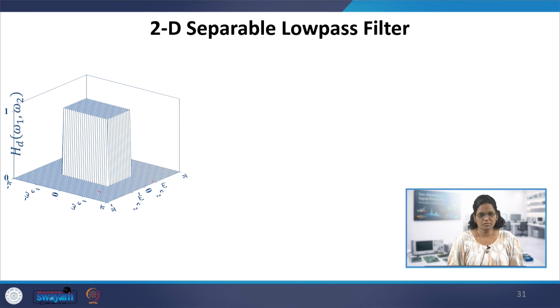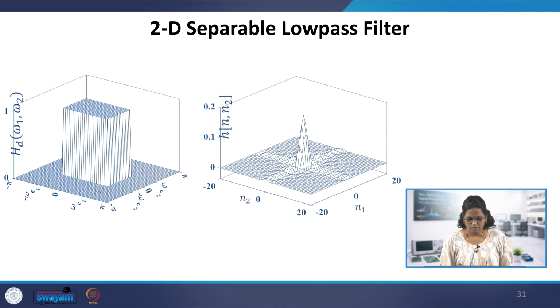So this has the frequency separable response, and we choose the frequency sampling filter in which we have obtained the sinc functions. If you recall, whatever the k values we need, those need to contribute to the frequency response in that sense. So this is the impulse response that we get. It is separable, so you can see the ripples at the center of the response.